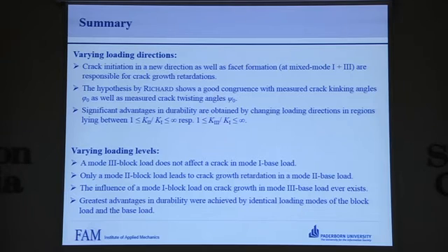The varying loading levels show that the mode 3 block load does not affect the crack in the mode 1 base load. Furthermore, only a mode 2 block load leads to a crack growth retardation in the mode 2 base load. The influence of a mode 1 block load on crack growth in a mode 3 base load always exists. The greatest advantages in durability were achieved by identical loading modes of the block load and the base load.